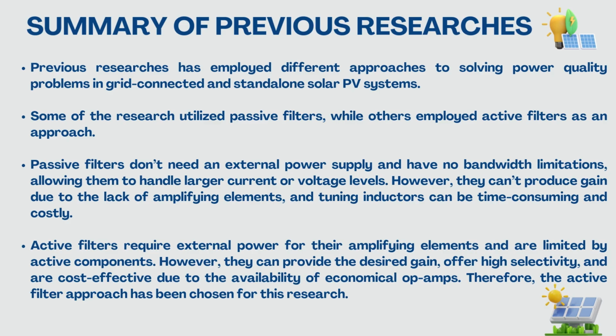Passive filters don't need an external power supply and have no bandwidth limitations, allowing them to handle larger current or voltage levels. However, they cannot produce gain due to the lack of amplifying elements, and tuning inductors can be time-consuming and costly. Active filters require external power for their amplifying elements and are limited by active components. However, they can provide the desired gain, offer high selectivity, and are cost-effective due to the availability of economical op-amps. Therefore, the active filter approach has been chosen for this research.